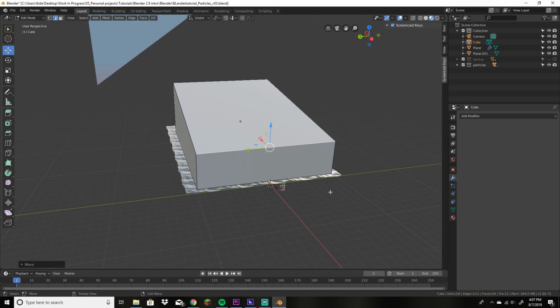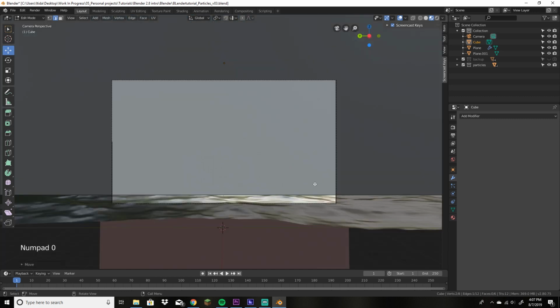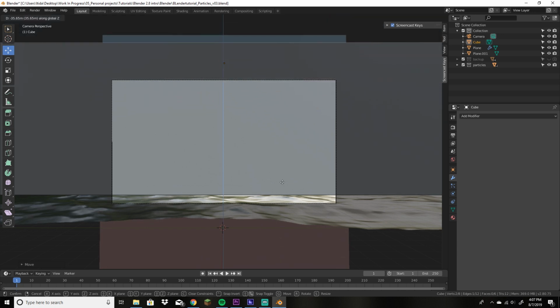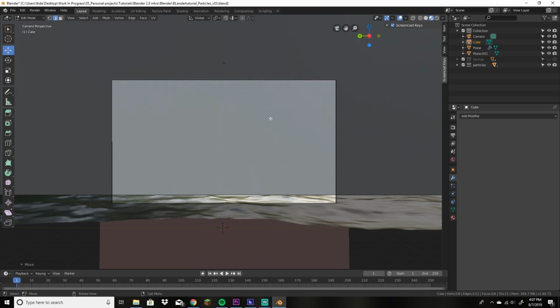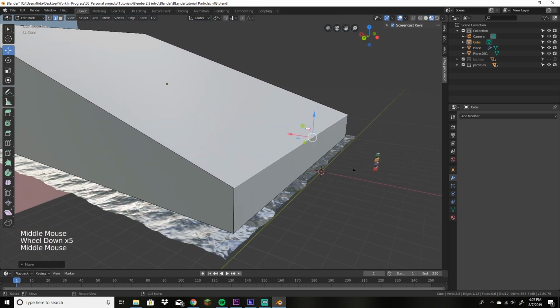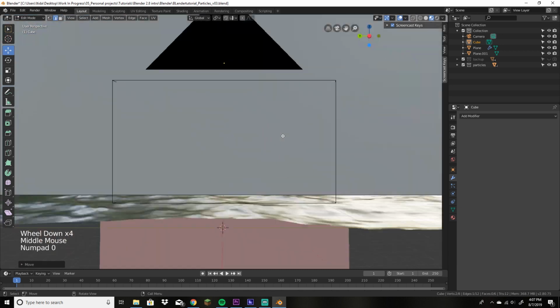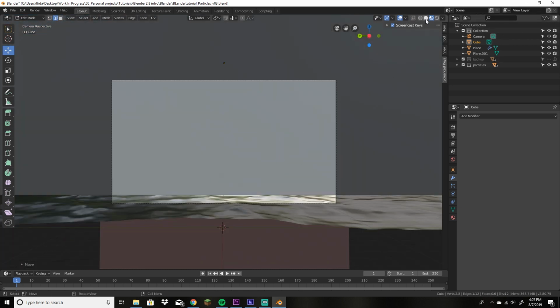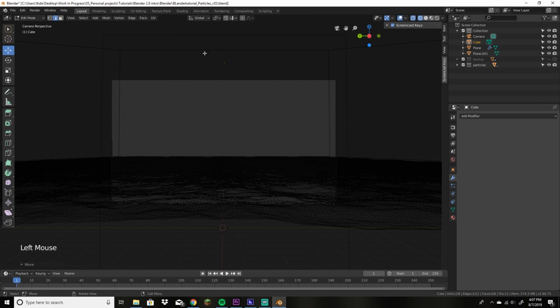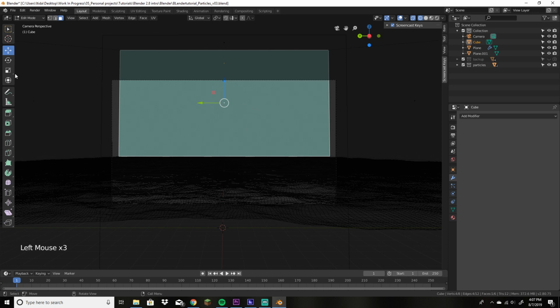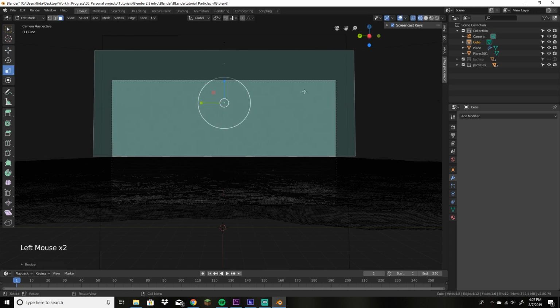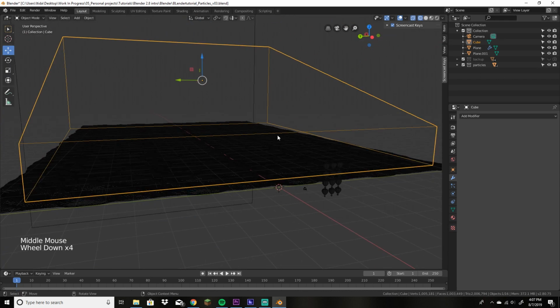And so to save our computer from generating things it's not going to use in the actual image, I'm hitting G, Z, and bringing it to about there. So I'm going to go back there, and I'm going to hit wireframe, so I can see where the top of that is. And looks like it could be a little wider in the back yet. So if I just select here that back plane and scale it along the y-axis, just so it gets out of the frame. So that's where all of our particles are going to show up.